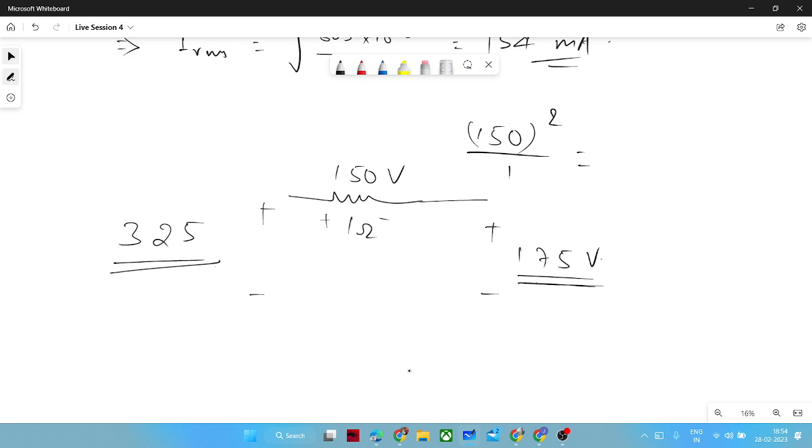It is really good in that it drops your voltage during the inrush period and limits your current. Whatever the total resistance, it will add on. Let us assume your load has something like 0.5 ohm. It will limit your inrush current by at least three times.